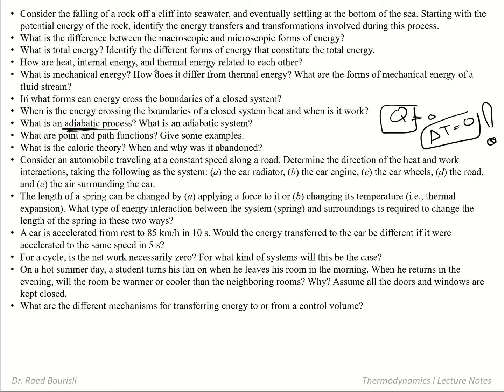I can have an adiabatic process where I insulate the thing pretty well, and then I could add energy using boundary work. So the temperature will increase as a result of this compression, not as a result of heat, but as a result of work.